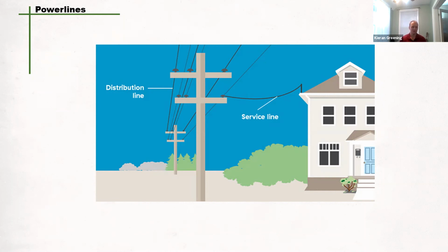Section 259: an employer or contractor shall accurately establish the location of all underground pipelines, cables, conduits in an area where work is to be done and shall ensure that those locations are conspicuously marked before commencing work using power tools or powered mobile equipment on an excavation, trench, tunnel, excavated shaft, or borehole, or before breaking ground surface with any equipment to a depth that may contact underground utilities. So underground utilities can be anywhere from a foot to quite a bit deeper than that in the ground. So it's very important that we get those lines located.